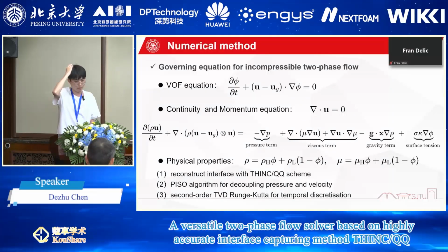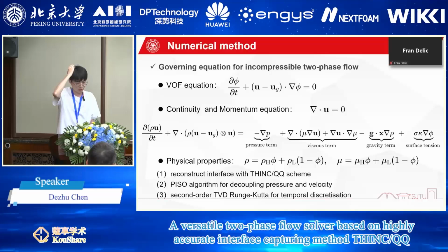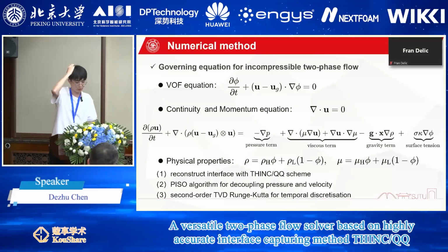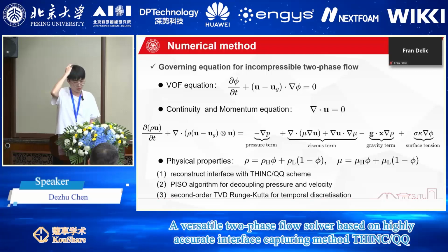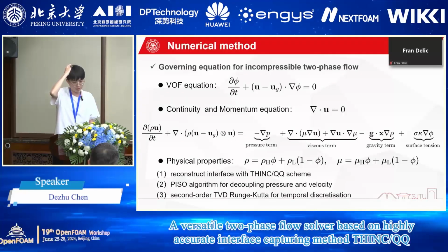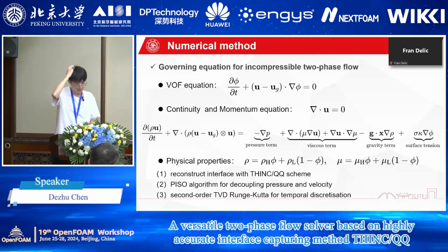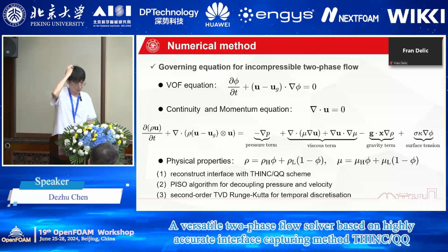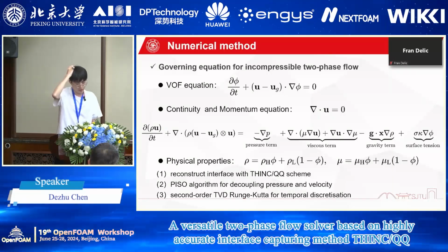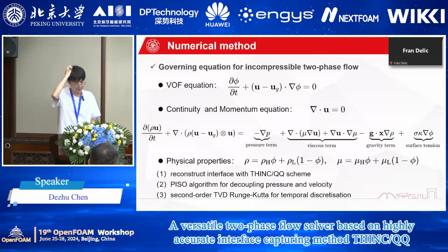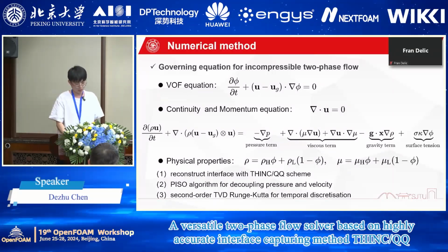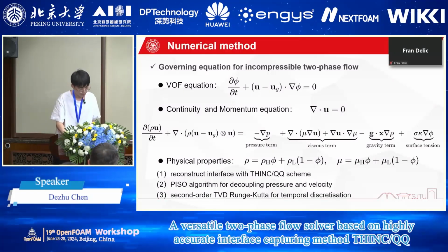About the solving of continuity and momentum equation, we use PISO algorithm to decouple pressure and velocity, and also to increase the accuracy of temporal discretization, we use second order TVD Runge-Kutta method.